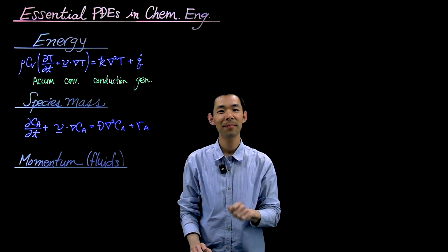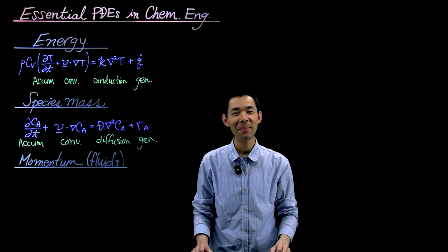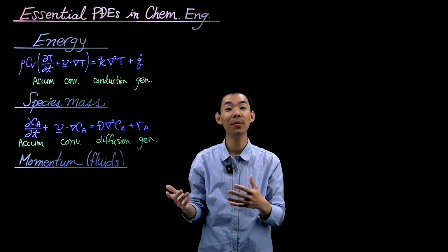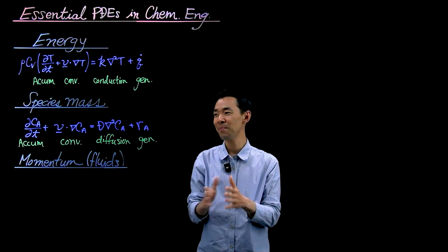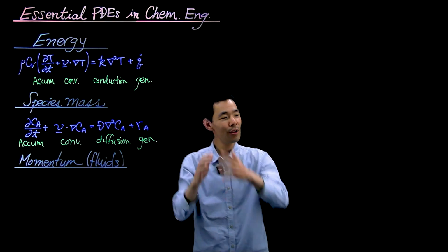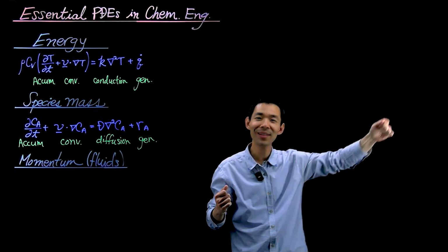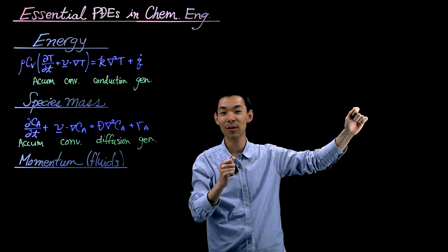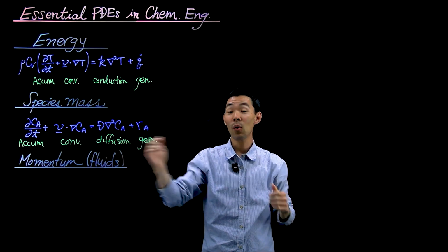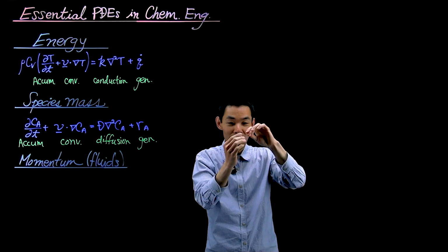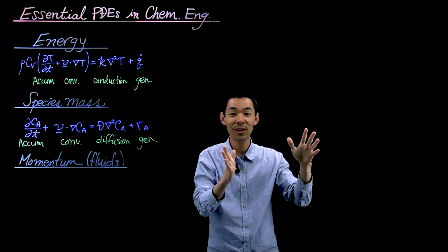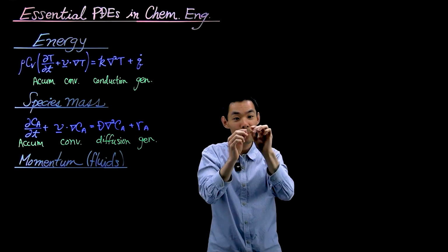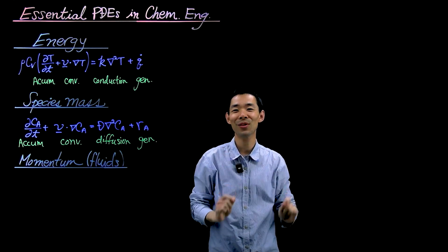Again, let's label each term. Once again, it's the same four categories of accumulation of some salt or some chemical species A inside your control volume. Second term here, convection. You can have fluid flowing that convects your species along your control volume, just the same way you can convect energy across your system. Right-hand side, we have diffusion, molecular diffusion of little solute species moving along your system due to thermal diffusion. Not convection of bulk material flowing, but of random hopping of species across your material.